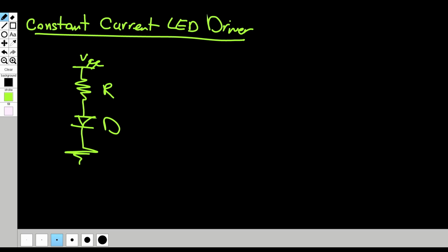So we can basically turn on an LED with a simple resistor circuit, right? We can have a source, let's call it VCC, over here. We could have a resistor and then we connect that to an LED and then that's a ground, right? So we have the LED here, we have the resistor here, and if you just connect it to the plus volts, it could be anything like 3 volts, 5 volts, or anything. You connect it to a resistor, and following that in series, you connect it to an LED or any sort of a diode, right? So this is a simple circuit, right?